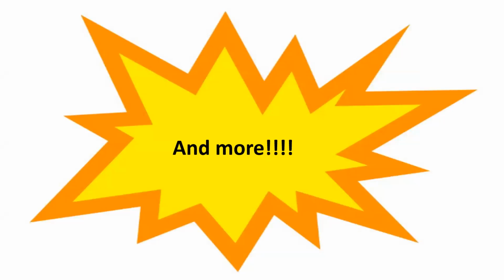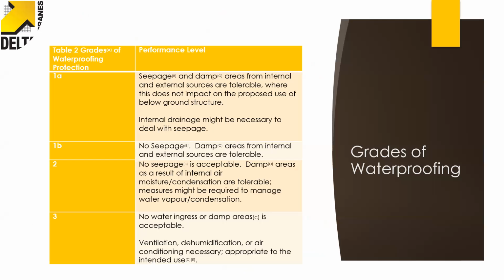And there is more in the new standard in terms of updates, but I don't need to go into that. I mean, that's far more than enough. So yeah, going back to grades of waterproofing, one of the first questions I ask is, what's the basement going to be used for? If it's a car park, I'll make certain decisions. And if it's a high spec office block or something, then I'll make other decisions.